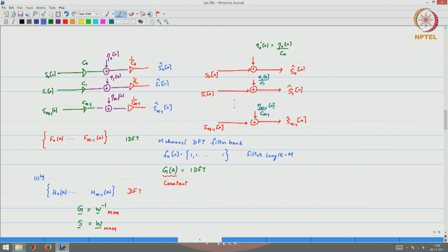And then when you look at the other end, if you want to bring all of the signals together, we can look at them as a scaling which will give you the resultant received signal. Equivalently, we can also think of it as parallel channels, all with equal gain but with different noise terms. Different noise variances means different SNR. So again, you can think of it as scaling of the signal with all of them having the same noise variance, or same signal power with the noise variances being modified. Okay, so this was the beauty of OFDM, and it has become one of the most widely used transmission techniques, and I believe it will be used as we move forward as well.